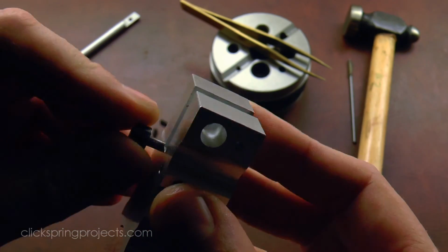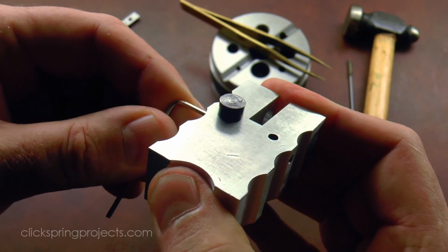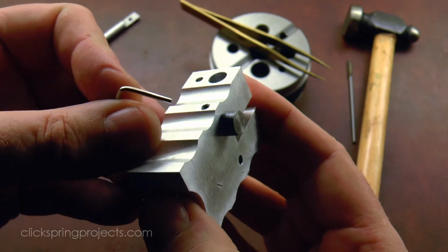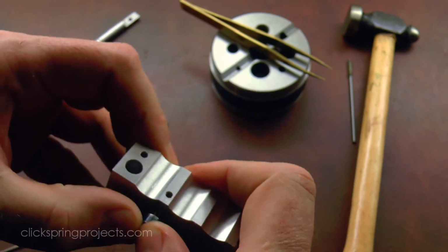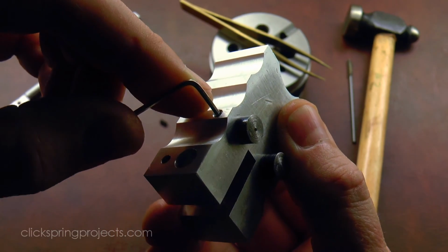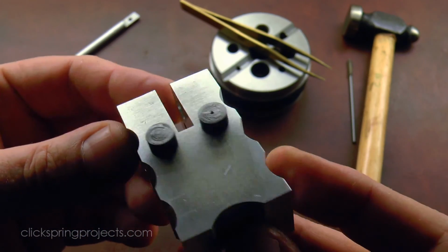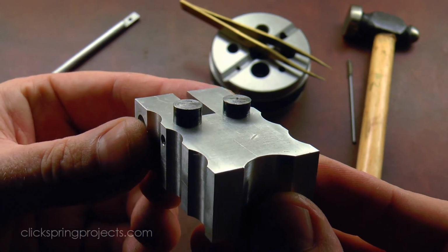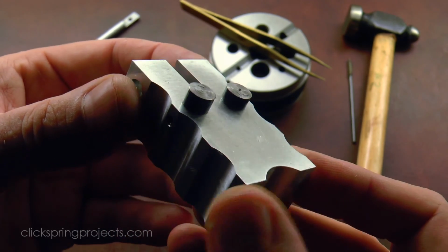The buttons are designed to insert in the unthreaded openings, and for this next machining step, we'd like them seated dead flat on the carrier for maximum rigidity. Once in position, they're locked off with a side grub screw. So what we have here is an excellent little fixture to hold the button cutters while we mill a rake angle on their top surface.